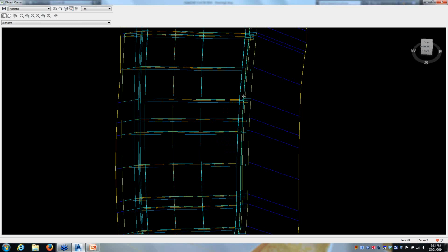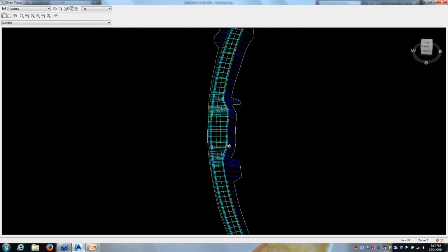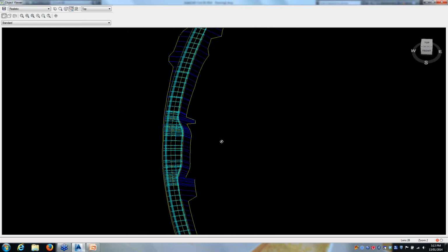So we've got a 2% crossfall at the moment for that little bus bay, but perhaps we've got driveways and things we need to match levels for along the edge of the bus bay. As well as widening it horizontally, we can change the edge of this using a profile on that alignment that we drew. So that's just another target. Let me show you how to use that target. We'll do something fairly extreme, but it'll just show you how you can modify both the width and the height of the edge of these roadway lanes.